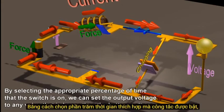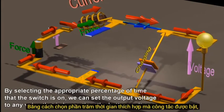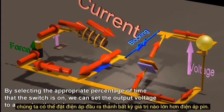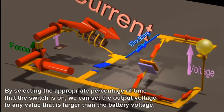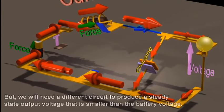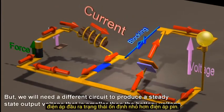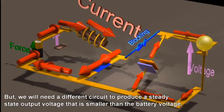By selecting the appropriate percentage of time that the switch is on, we can set the output voltage to any value that is larger than the battery voltage. But we will need a different circuit to produce a steady state output voltage that is smaller than the battery voltage.